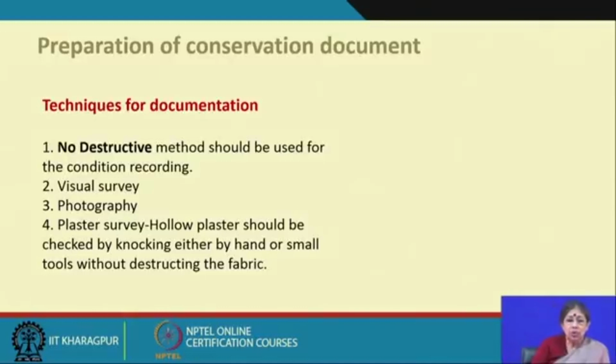Now, techniques of documentation, because we are saying that we also have to understand the causes of decay. In that case, we know that the structure is already there. So, one very important thing to remember is that no destructive method should be used for the condition recording. As I say, we have to understand the foundation. So, there are foundation investigation methods which work without damaging the structure.